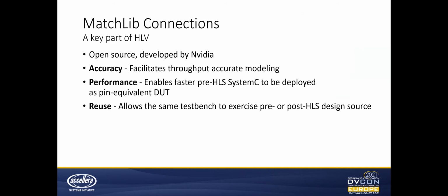All right, so before we go any further, we need to discuss Matchlib Connections. I mentioned this earlier, and I'll describe it in a little bit more detail here. This is a library of commonly used functions and components that was presented by NVIDIA at DAC in 2018. It defines things like interfaces, FIFOs, and interconnect, and it includes a set of latency-insensitive ports and channels along with an API for their use.